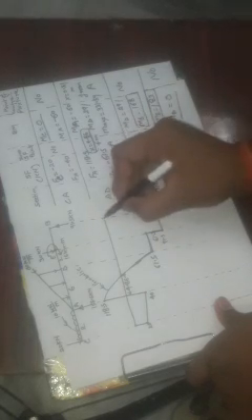From D to B there is a point load, so there will be a constant line, as already mentioned during the analysis on the previous pages. So it is 91.5. Close the curve. So this is the required shear force diagram for this case, right? Now draw the bending moment diagram for this portion.